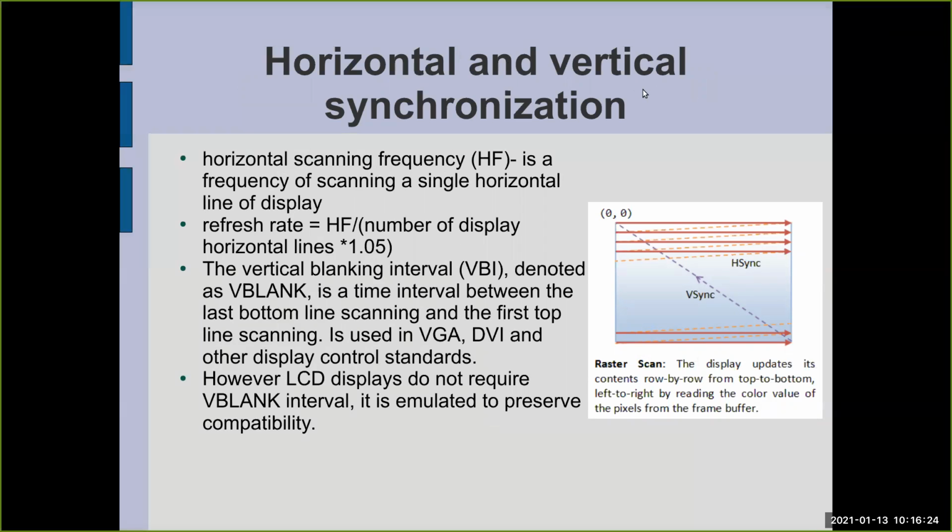It is horizontal and vertical synchronization. So the image was drawn line by line. So this time is called horizontal sync. So after drawing a line, the ray was silently moved to the beginning of the next line, and so we have here an h-sync period. So the period in which the beam is not working, and the magnet moves it to the beginning of a new line.